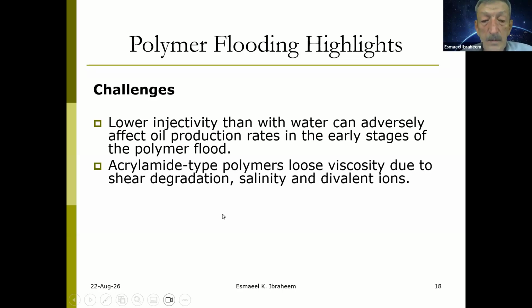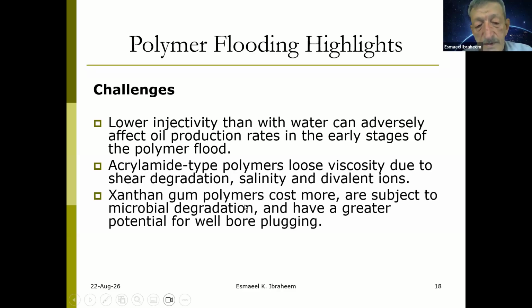Also, acrylamide type polymers lose viscosity due to shear degradation, salinity, and divalent ions. When you have salinity and divalent ions, the viscosity of the polymer degrades. Also, xanthan gum polymers cost more.